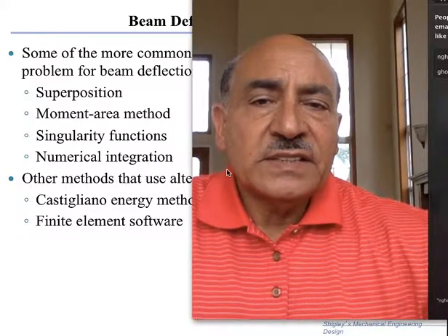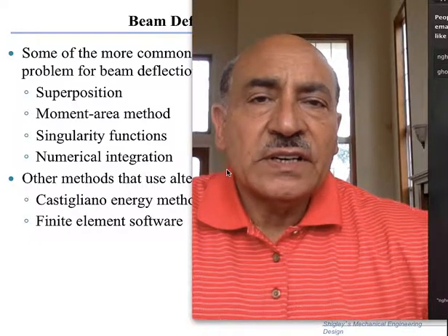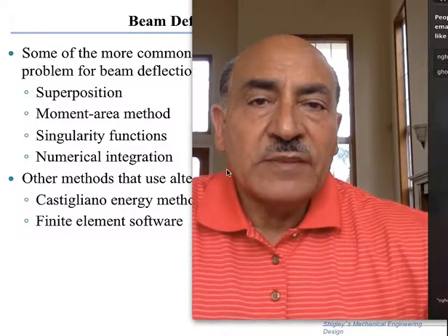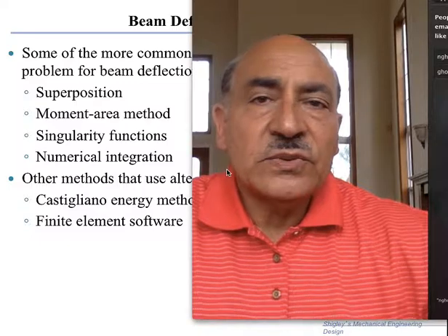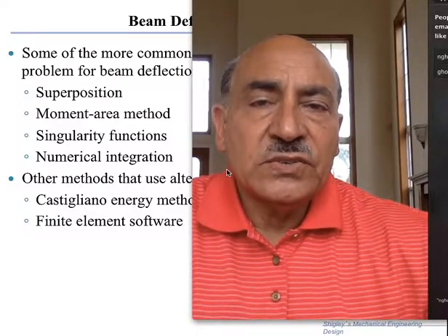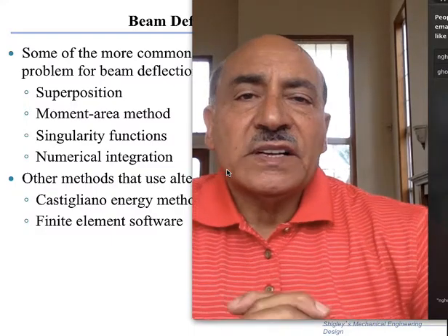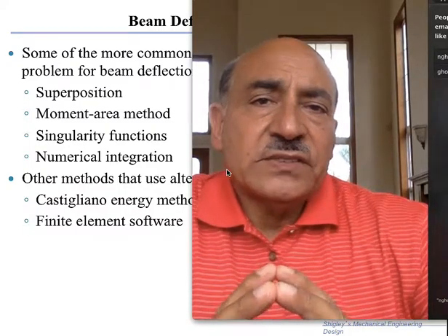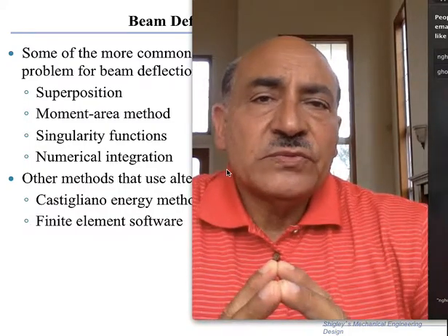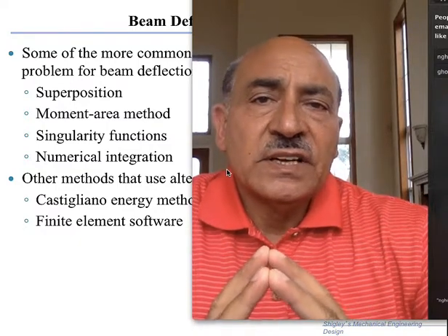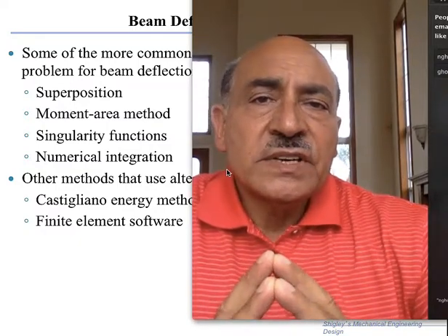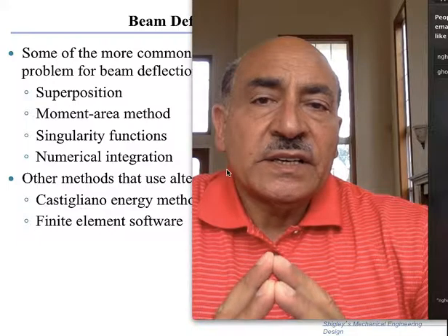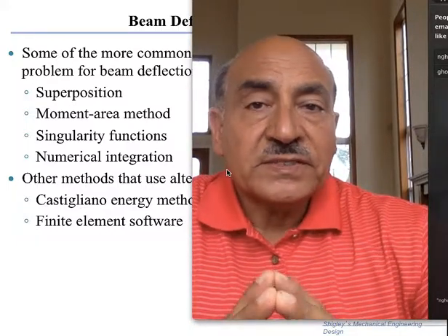Next is the numerical integration, and that is just solving a differential equation of the fourth order, d4y by dx to the power 4 equals the applied load q as a function of x, and then we would do numerical integration. This is not really what we would like to use, and if we're going to go in the numerical direction, then we would prefer to use the finite element method rather than pointwise integration of the deflection equation.